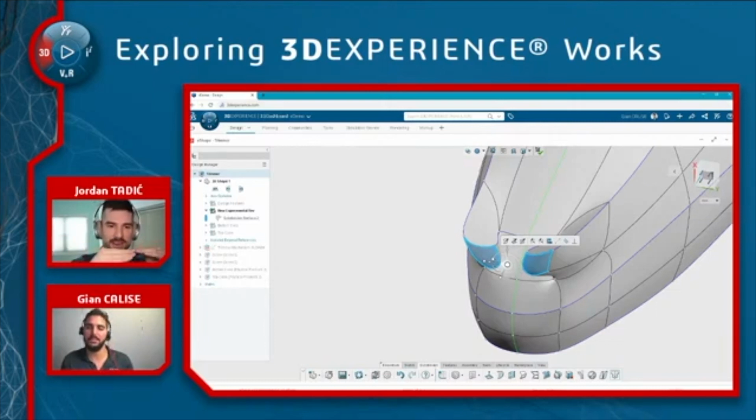those two surfaces together? Like on the toolbar, there was a merge feature. Yeah. And that appears in the surface mode when you're selecting edges. When you're dealing with 3D geometry and you have opposing faces, you can actually click the extrude feature on that context toolbar. And rather than extruding those individually, since they're within a close enough vicinity of each other, it'll just blend right together.